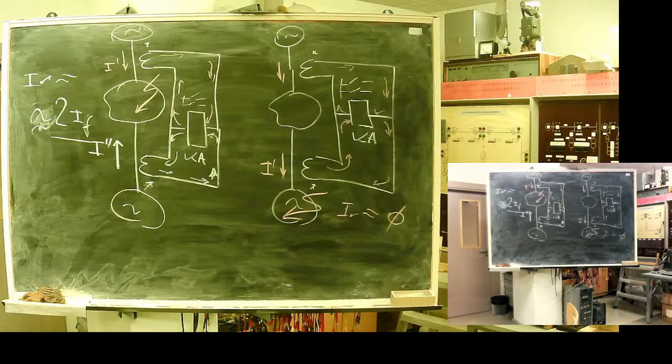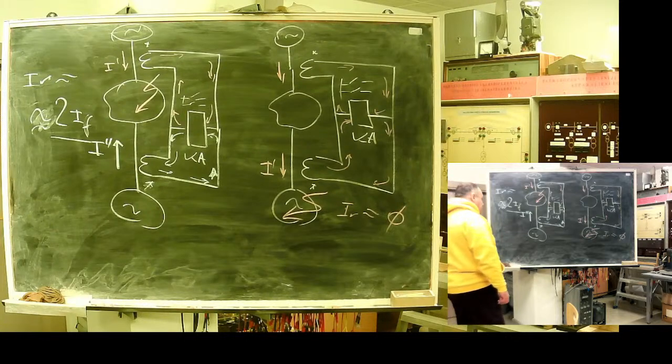Overcurrent protection and distance protection rely on relative selectivity. Selectivity is achieved with different operation currents and, what is important, with a time delay.